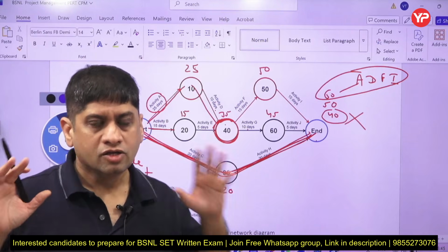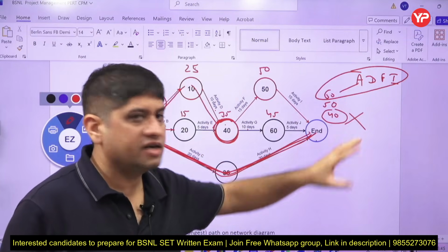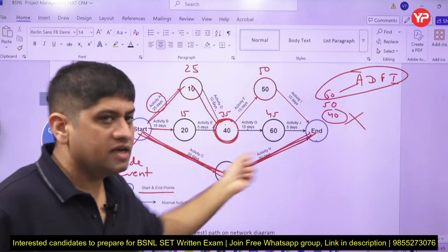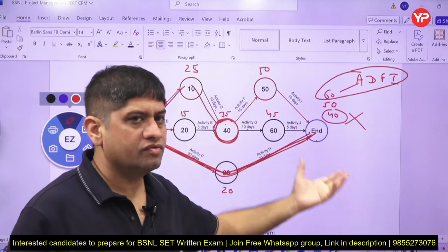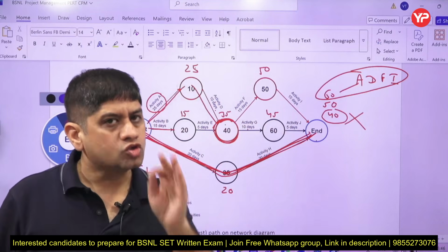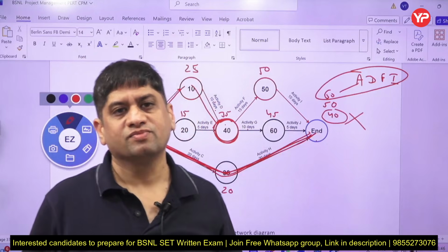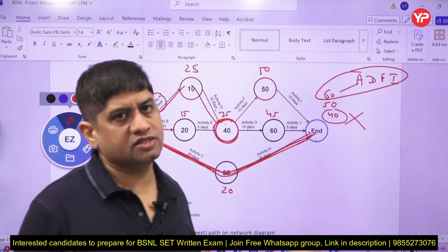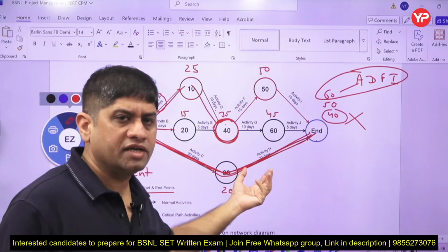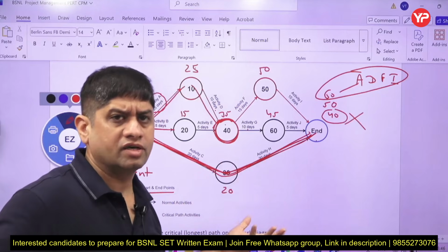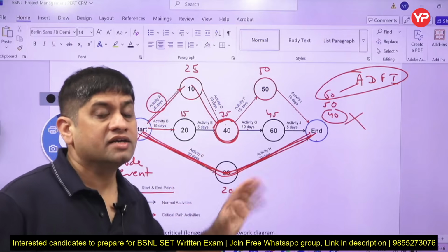So the time in which A, D, F, I are completed, 60 days, in that time C and H will also be complete. In that time B, E, G, J, which takes 50 days, will also be complete. So all the activities will be completed minimum in 60 days. And when 60 days are hit, our project is complete. No doubt here C and H only take 40 days, so they have 20 more days left for them. That is called a kind of float. Float means buffer कितना बच गया, उसको float बोलते हैं कि कितना buffer बच गया.